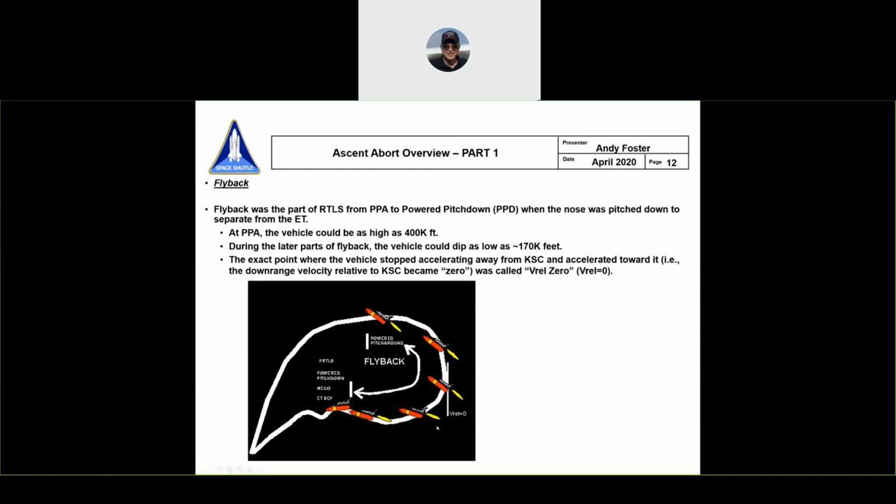The bottom of this curve down here, the trajectory, could be as low as about 170. Usually you come through here at about 180 or 190, and that'd be pretty good. I get nervous once I start seeing about 170. Why? Because I'm worried about aerodynamic heating of the external tank through here. But usually 170 was about the bottom limit.